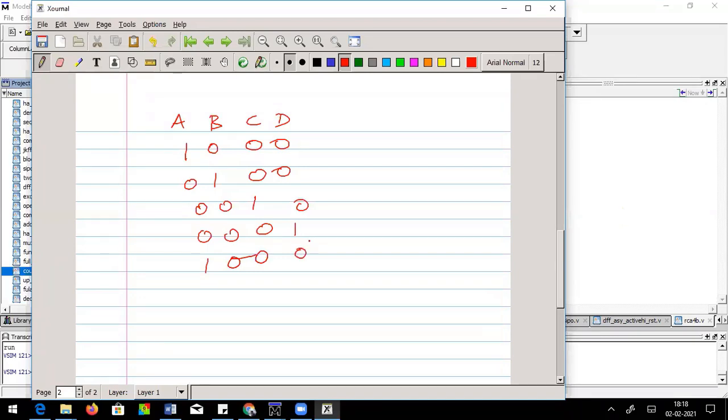If it is not the ring counter, you can just convert this ring counter to a Johnson counter also. So first, if it is like this, second count, it comes like this. Third, it comes like this. Fourth, it comes like this. Fifth, it comes like this. Then again 1, like this. So instead of 0, you will have a subsequent 1 coming up. Now let's try whether that's working.